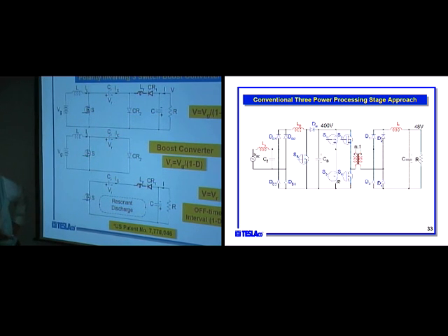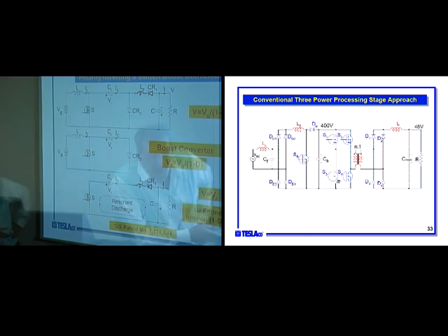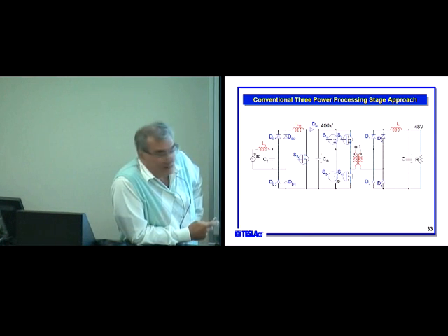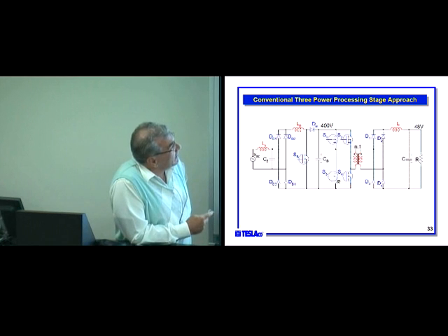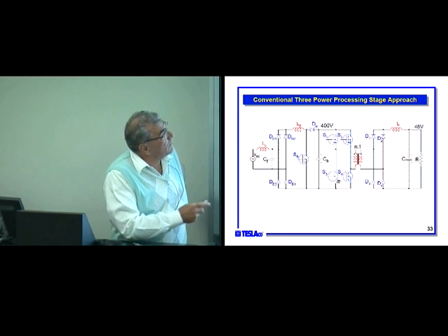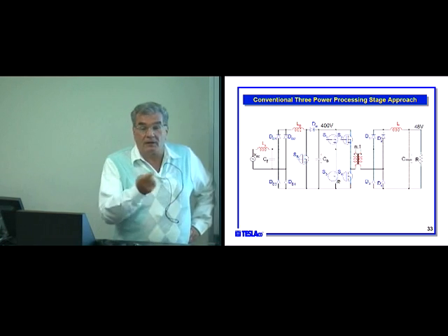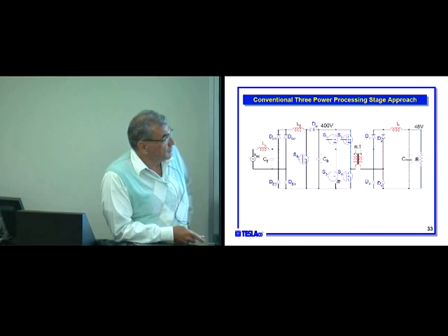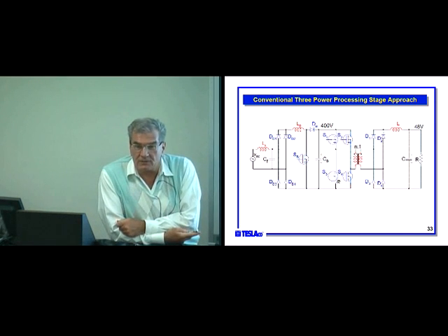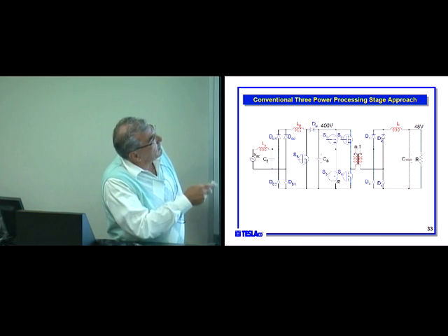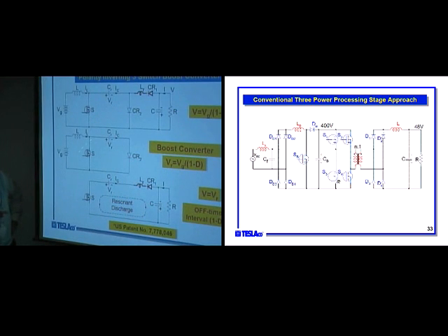This is a diode. And the diode says, I will never turn off until this inductor current goes to 0. And my circuit works that way, that I resonate in this way, and when inductor current goes to 0, then it turns off naturally. All right, so now, how do we get 3 switches? Funny thing. Look at this part here. Doesn't this remind you of just like that boost converter, except the position of the diode, the capacitors are interchanged, right?